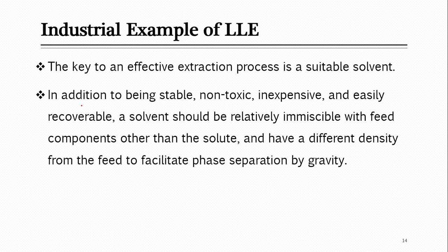So that's the solvent, in addition to being stable, non-toxic and inexpensive. First of all, it should be stable, it should not be reactive with the components of the feed. You have to select such a solvent which is stable, non-toxic, inexpensive and easily recoverable. This is also necessary because we have to reuse it, so it should be easily recoverable.